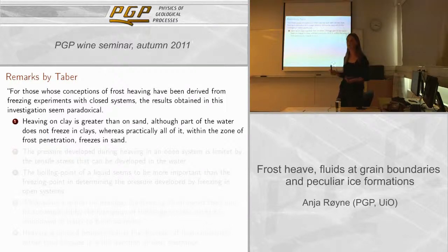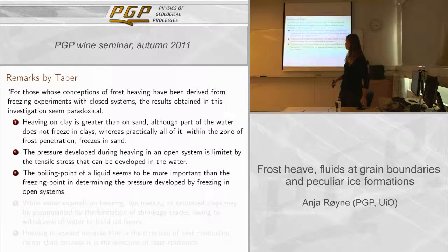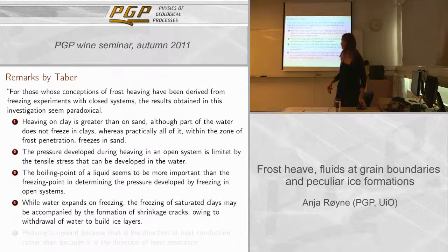So more of the original water freezes in sand, but the heaving is more in clays. And then he talks about this tensile stress in the water, and that maybe the boiling point of a liquid seems to be more important than the freezing point in determining the pressure developed by freezing in open systems.